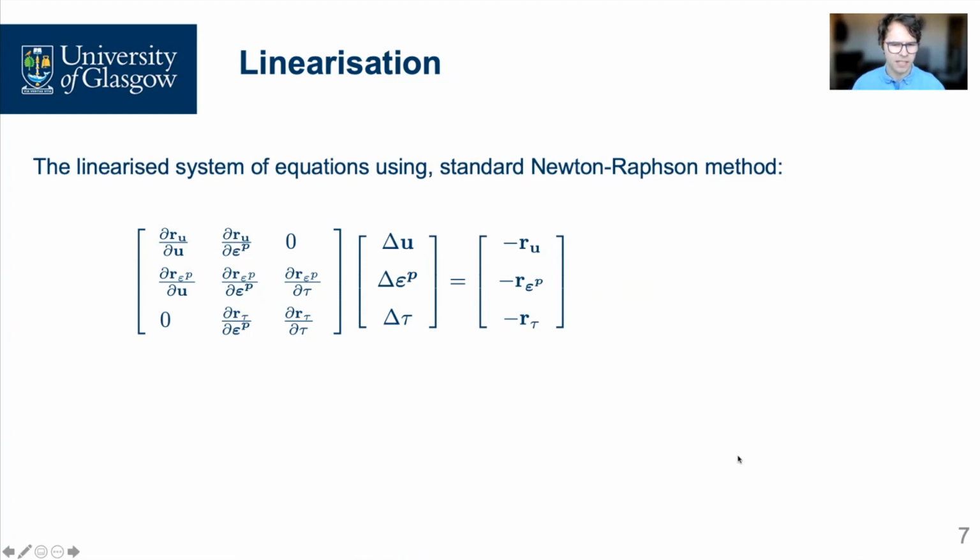Typically, classical nested approaches solve the evolution equations via local Newton method on the integration points with algorithms like closest point projection, and then use another global Newton solver to solve the entire system for displacements.